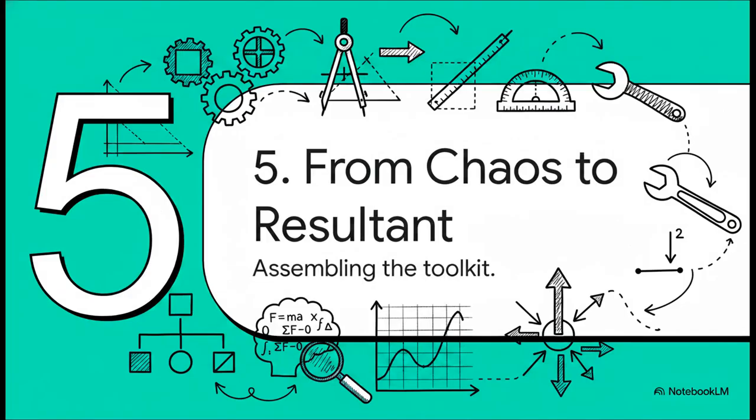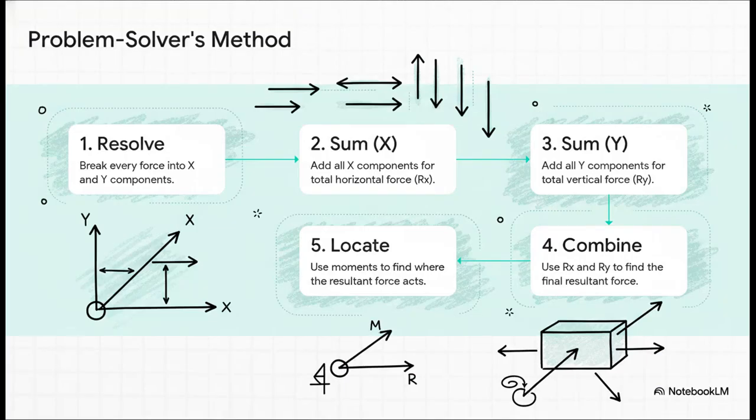All right, it's time to put all of our tools together on the workbench. We've got our classifications, we've got our geometry tricks, our analytical components, and this idea of moments. Let's see how they all combine to solve pretty much any problem we throw at them. So here it is, the complete problem solver's method. Step 1, resolve every single force into its x and y bits.